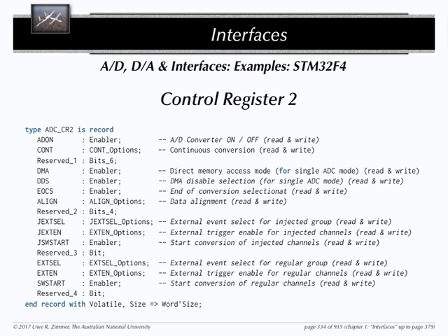So whenever you set, for example, the continuous conversion status of your device, you can only use the values which are defined in your enumeration type for that. You can only use continuous or single as defined here. You cannot use red or green or any other enumeration type. You cannot use 0 and 1. If you try that, the compiler will tell you this type doesn't match. You can only use that type for that purpose.